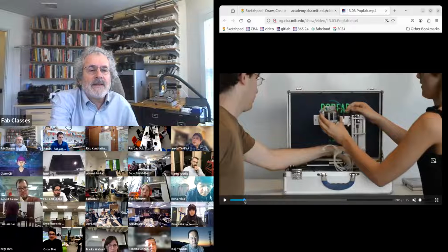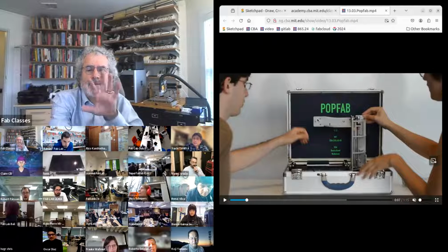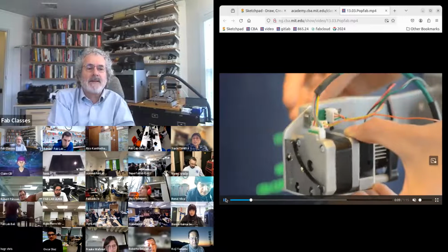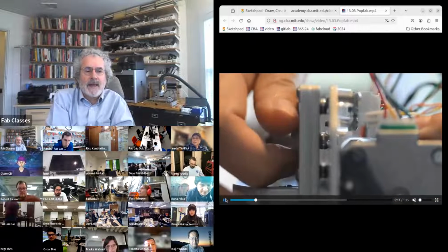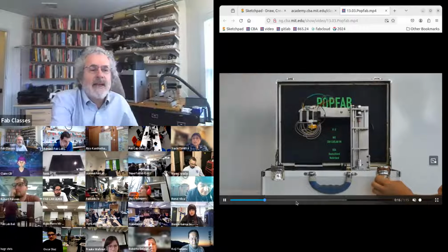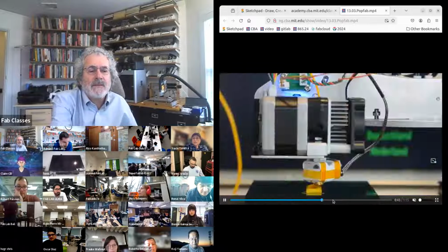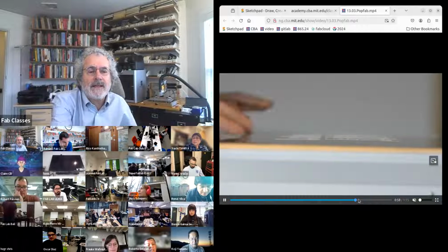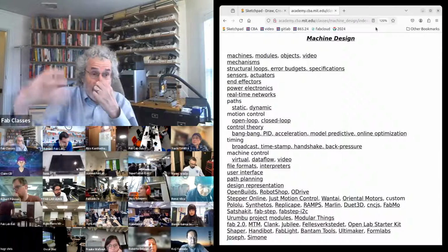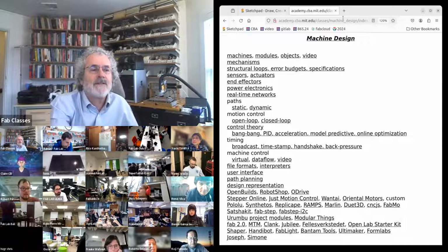Let me go back slightly. You'll see right here, those 3 balls. That's for a kinematic mount. And so here, Nadia's going to snap in a 3D printing head, and the kinematic mount accurately aligned it. And then this machine had multiple heads. So along with the 3D printing head, it had a spindle for milling. It had a knife blade for cutting. And so the end effector is the thing that does the work. And that had modular end effectors.